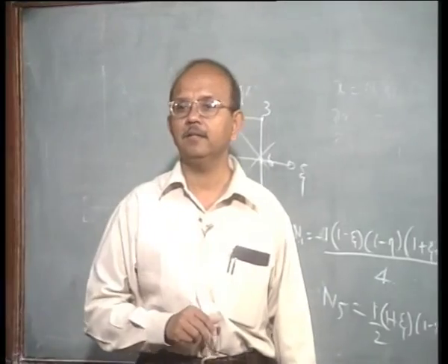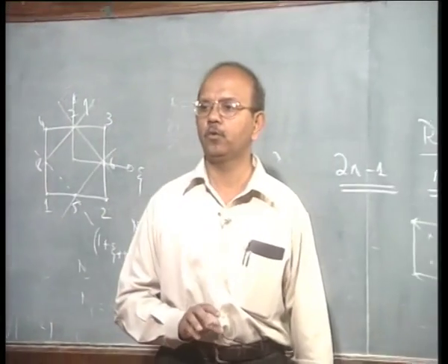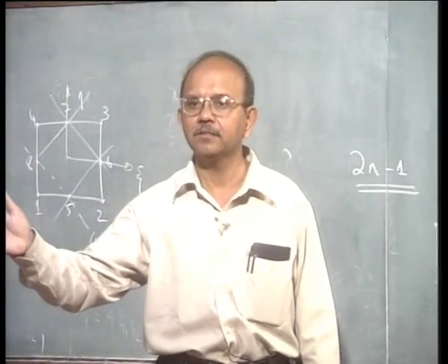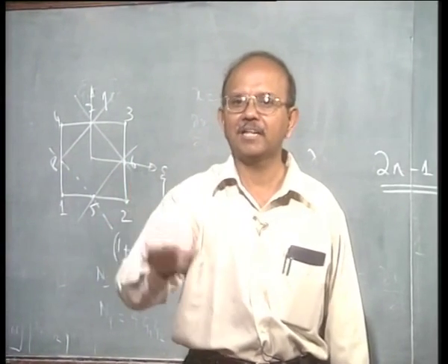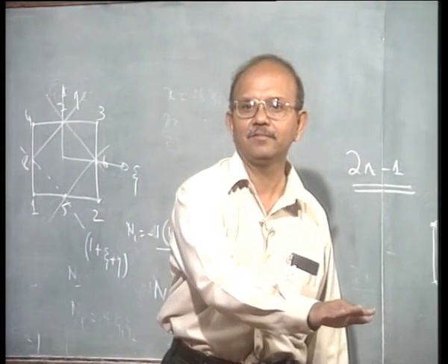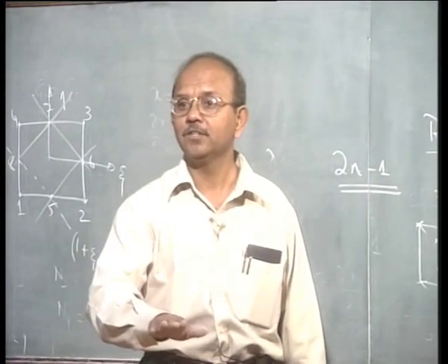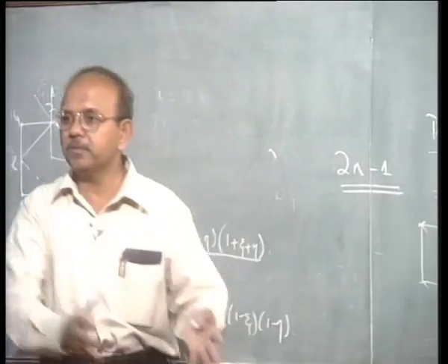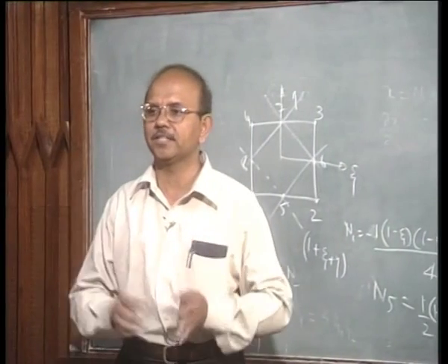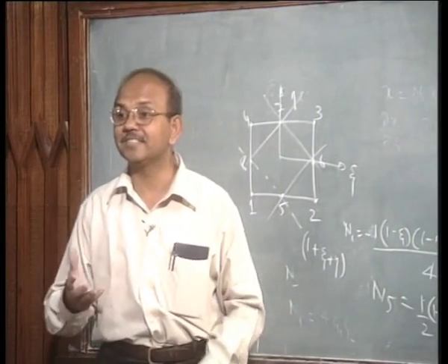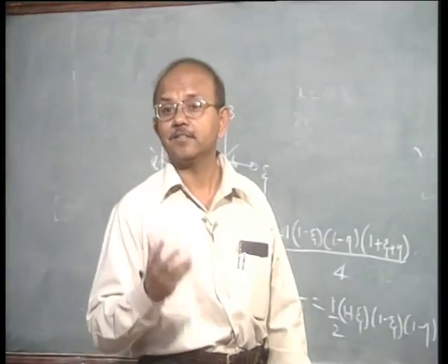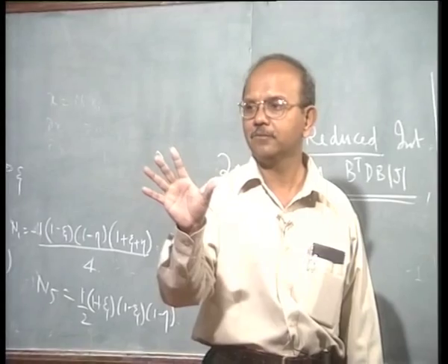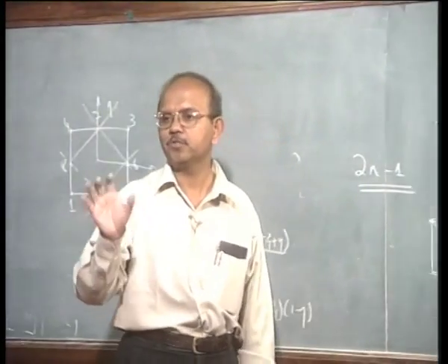On the other hand, when I go to the 1 by 1 rule, that error is in one direction, I introduce another error in another direction, the structure softens. So it so happens that this error, though I know it is an error, tries to compensate for another error which I have introduced due to discretization, and hence ironically gives better results many times, I mean with a warning, ironically gives better results.